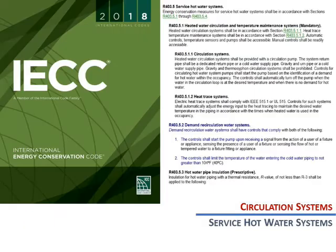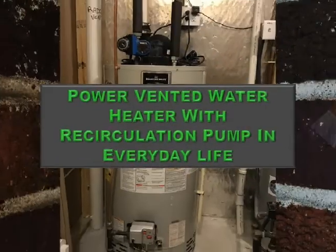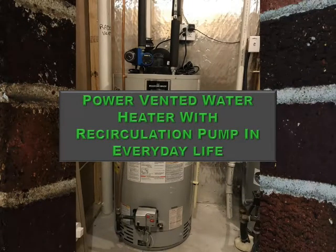If you install a circulation type system or a demand recirculation type system, we have a couple of different sections, 403.5.1.1 and 403.5.2, that require controls for these types of systems. Any of those systems are going to require hot water piping to be insulated to a minimum R-3. Power vented water heater with recirculation pump in everyday life.